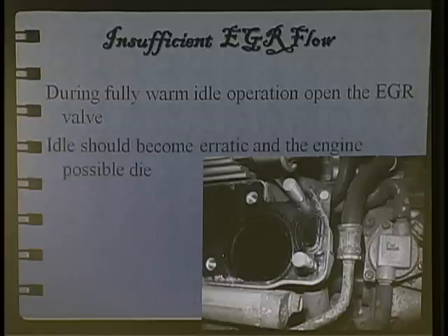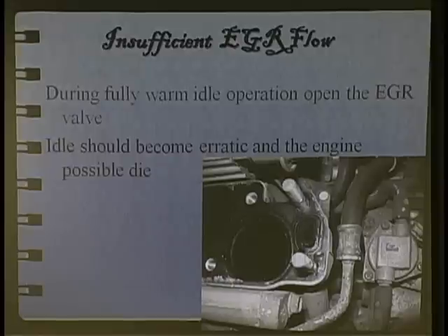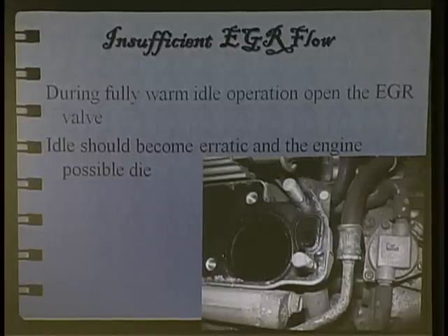But during warm idle operation, open the EGR and the engine should run erratically. I mean, on OBD1 GMs, didn't we use a green rag to test EGRs? No, it was hot, so we reached around with a rag and opened the diaphragm with two fingers, or maybe you had one. Yeah, and then we expect the engine to die or run badly. Did we have flow? On a Ford, you've got to suck, because it's a vacuum-operated one, so you're sucking down air in the hose. Or you should use your handheld pump.